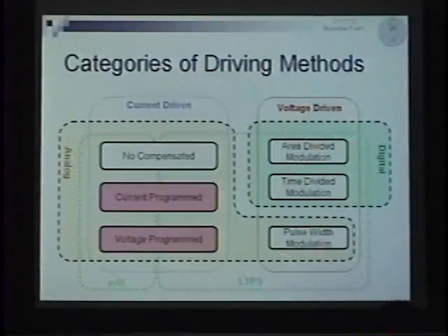But this driving method has a serious problem: since the OLED is driven by a constant voltage, the sticking image is very serious. If the OLED characteristics degrade, the luminance also decreases. So I think there is no chance for this driving method to be commercialized.